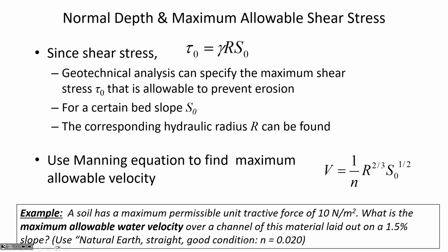So we'd seen this shear stress equation before, but I wanted to just point out that we can combine it with Manning's equation to find out maximum allowable velocities. Any questions about that?